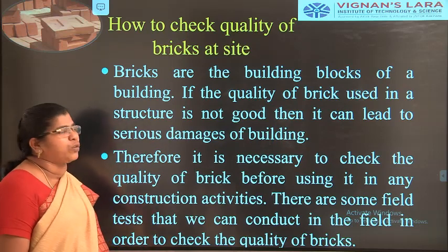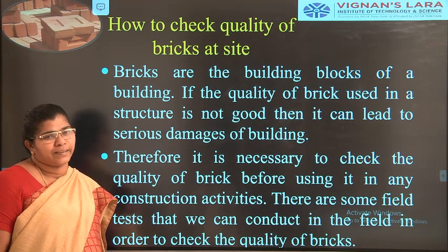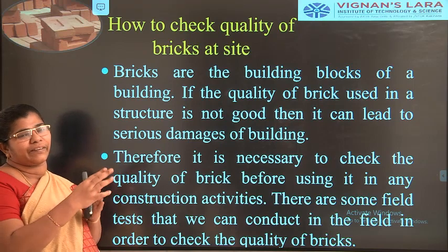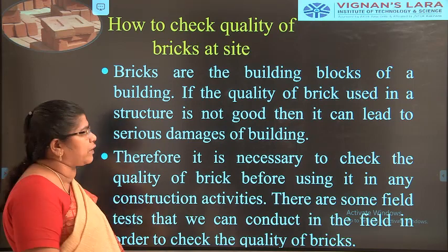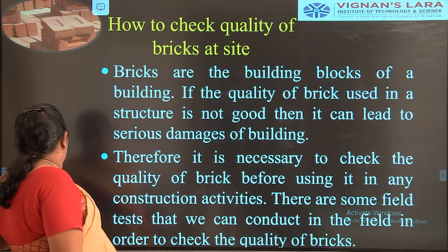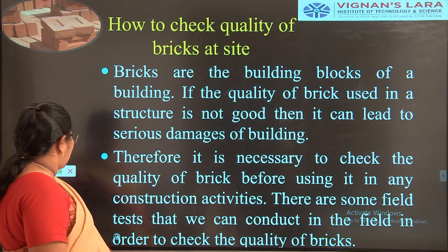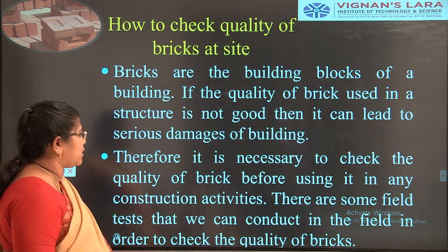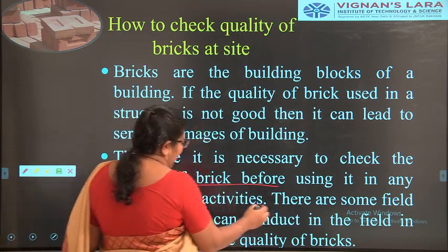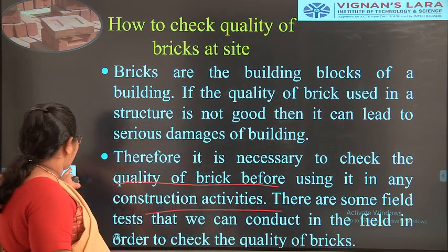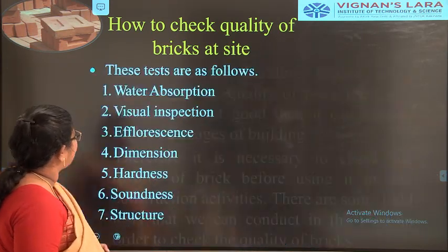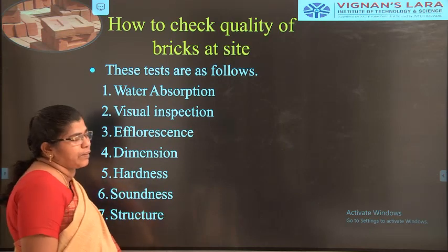Next we will see how to check the quality of bricks on a site. This is very important. One thing I am already telling you now: when we take two bricks and strike them against each other, they should give a very good clear ringing sound. Bricks are the building blocks, so we have to know about the quality of the bricks before using them in construction activities. So how do we conduct the tests? These are the tests that we will be adopting here.